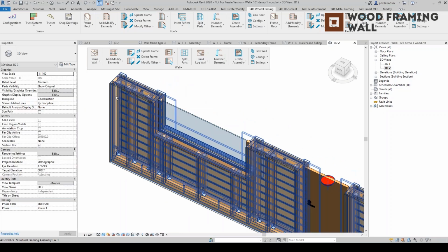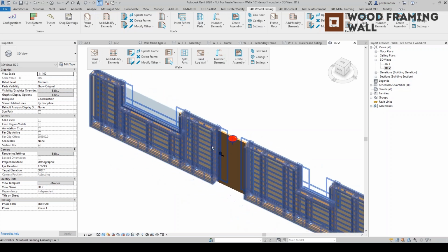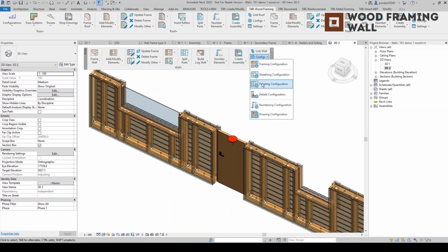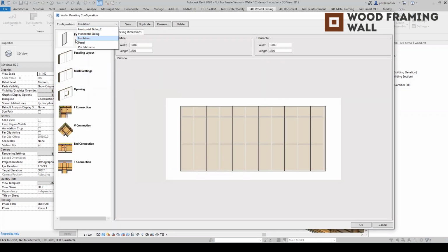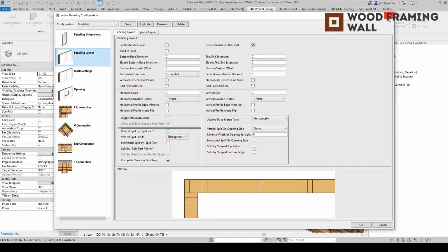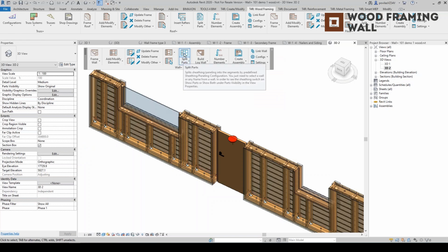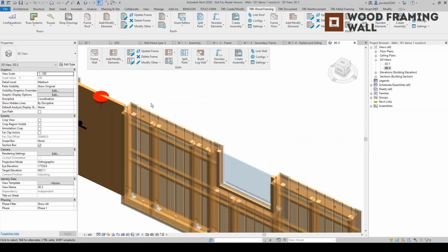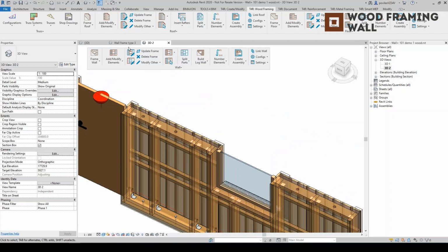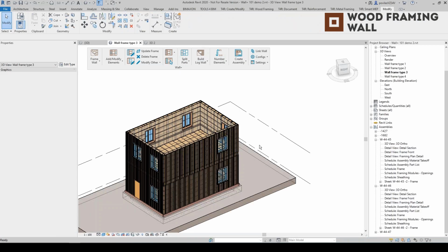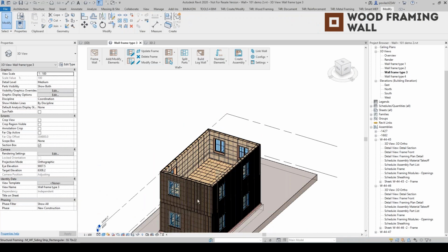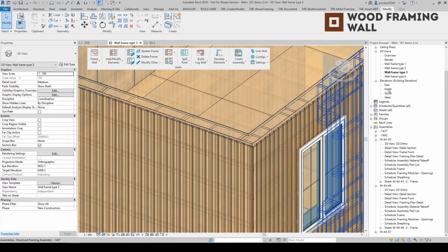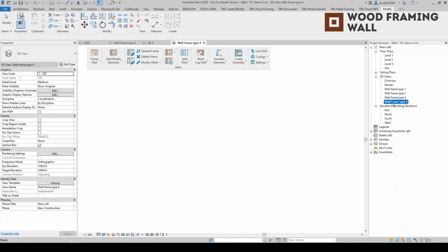The other great thing you can do, actually, you can generate your insulation in between the mainframe. So in between plates and studs, you can have your insulation layer. So that's done via panel configurations, where you can create your insulation configuration, define the size and the layout in those parameters, and just click on click to split parts, and it's going to appear automatically. Okay, and once this is complete with multi-layered walls are in place, so we go to the last example.